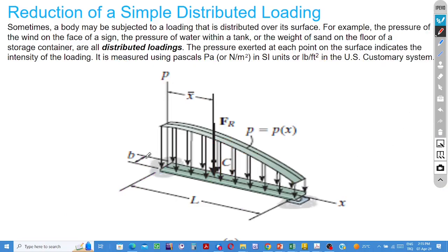Yes, if the distributed load is uniform in one direction but not uniform in the other direction, then when multiplying the given load, expressed as surface pressure, by the dimension of the contact surface in the direction where the distribution is uniform, we can have the load curve not in the unit of pressure but in newtons per meter in the SI unit system.